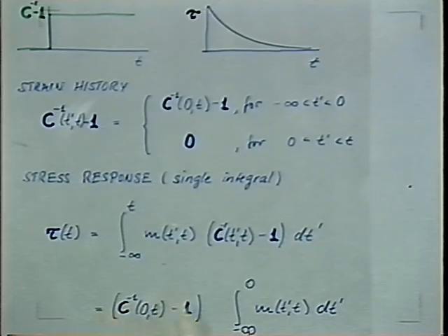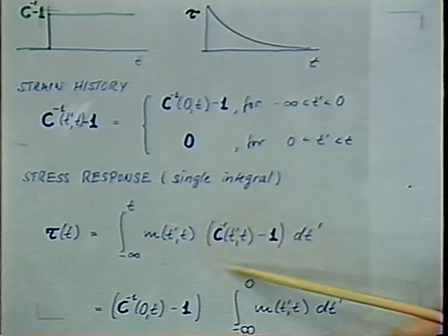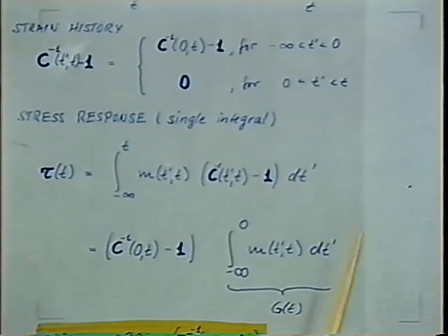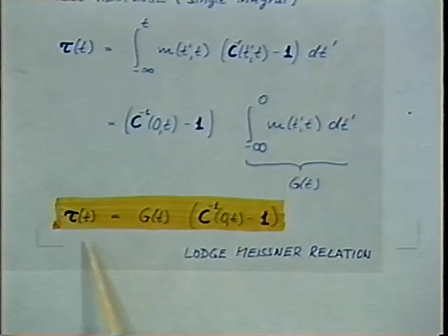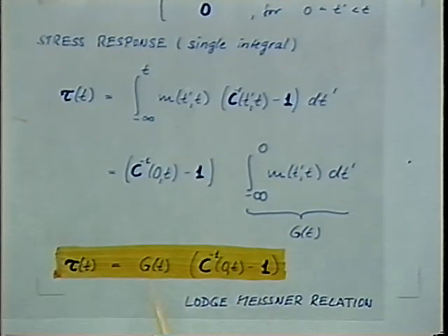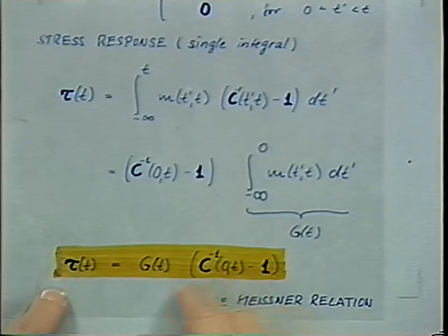And we are changing now the integral from -infinity to t as given here, actually using only the finger strain contribution. We put this outside and then obtain the same Lodge-Meissner relation for general formalism. You can really generalize that. You can say that the stress is given by a constant times the relaxation modulus. In all stress components, independent whether this is shear or extension or whichever component you're looking at, they are decaying with the same time function. And that's pretty close to what's being observed in experiments.